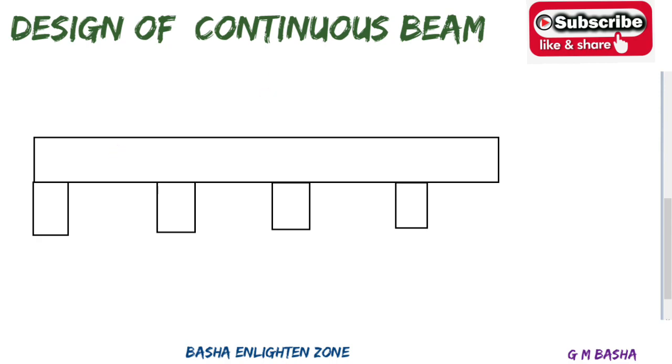Here we know the condition, one condition. What is the condition? There will be 3 bars of 12 diameter at the mid span and 4 bars of 12 diameter at the supports. Okay. Here we know one condition. For resisting of any beam, minimum 4 bars will be required.